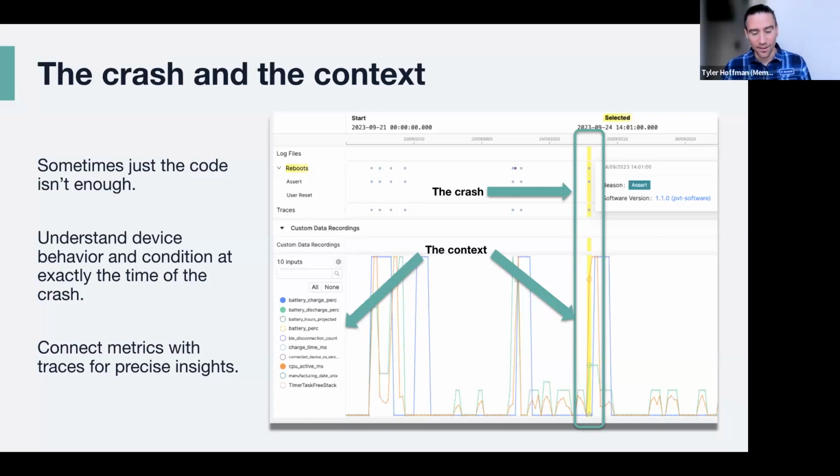And we would have various different bugs exacerbated by just the fact that these flash chips were becoming super slow. If the device is in the field for 2 years, it will exhibit very different bugs than if the device is basically coming right off the production line. And honestly, you have to fix all the bugs because your devices are still going to be in the field and people still expect to be able to use them properly.